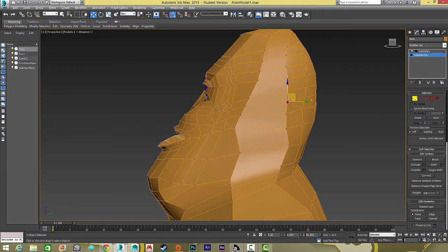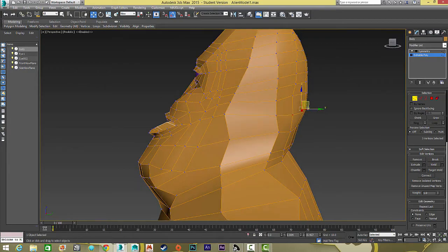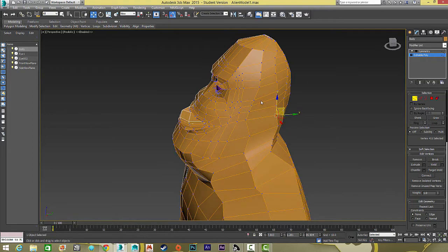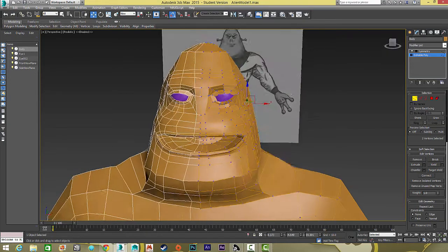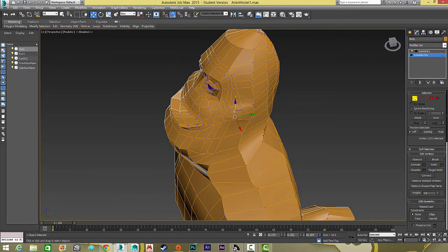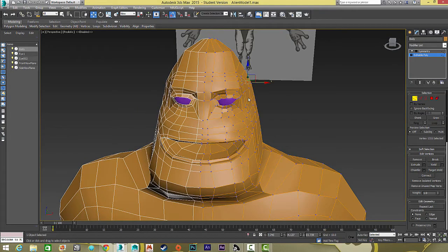But in doing this, you might actually mess up another area that isn't quite as clean. So we do still want to fan some of these out a little more. Try to clean up the head a little bit. This area right here is still a little boxy, so I try to smooth off some of these areas. Maybe some of these are fanned out a little more, so that things aren't so scrunched in areas. Some of these will need to be pulled out, as well as back. That one needs to go out.